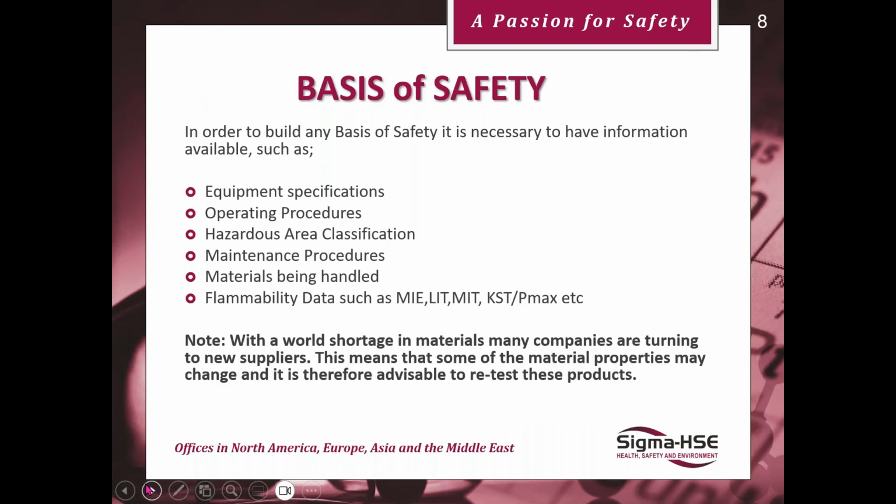Maintenance procedures. How do you look after your equipment? Are you reactive in its maintenance, or do you carry out a preventative maintenance structure? What materials are being handled? Are they liquids, gases, powders? Do you know anything about them at all? You'll need flammability data, such as MIE, MIT, LIT, KST, PMAX, etc. We'll talk about that in a few moments.